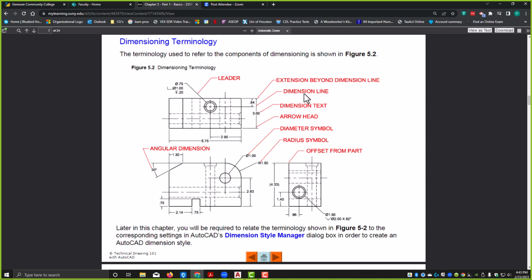Here on this circle right here, the dimension, the 0.84, it's excuse me, not a dimension line, it's a location dimension. That 0.84 you're going to see crosses the object line and goes all the way over to the center mark that's on this diameter over here.